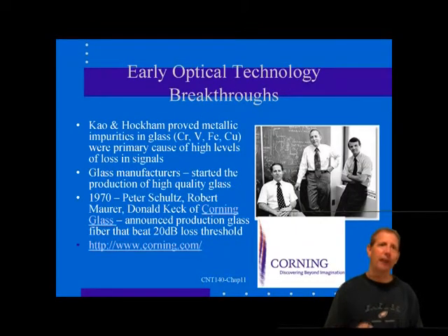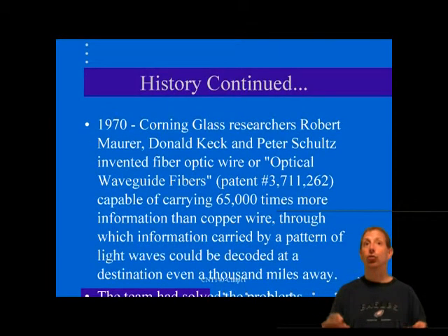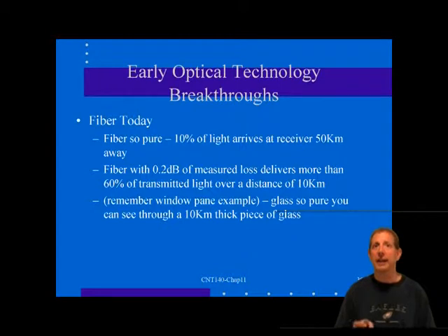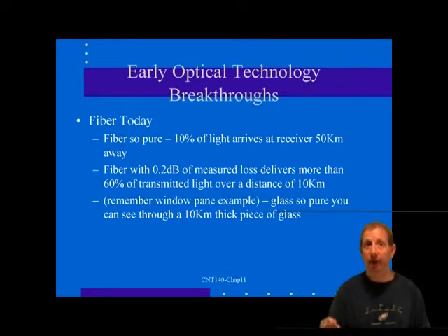The fiber's core actually transmits the light beam, while the cladding provides the strength, flexibility, and a controlled step in refractive index. All are necessary for proper fiber operation. Do not mistake the cladding for the plastic buffer and the primary coating that coat the fiber strand in a tight buffered cable construction.